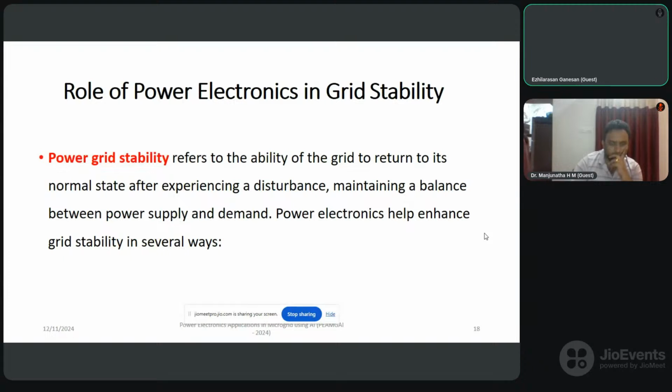Suddenly, the entire southern states won't be having power anywhere. Everything will come to a standstill. It means we have to take immediate action. So what they will do now, they will island a few generations, like those supplying airports, railways, and other such infrastructure, and they have to restart the entire plant again. That is the generator alternator, which has come to a stop. It will take a minimum of 2 to 3 hours to start the machine again, even if it is in islanded mode.